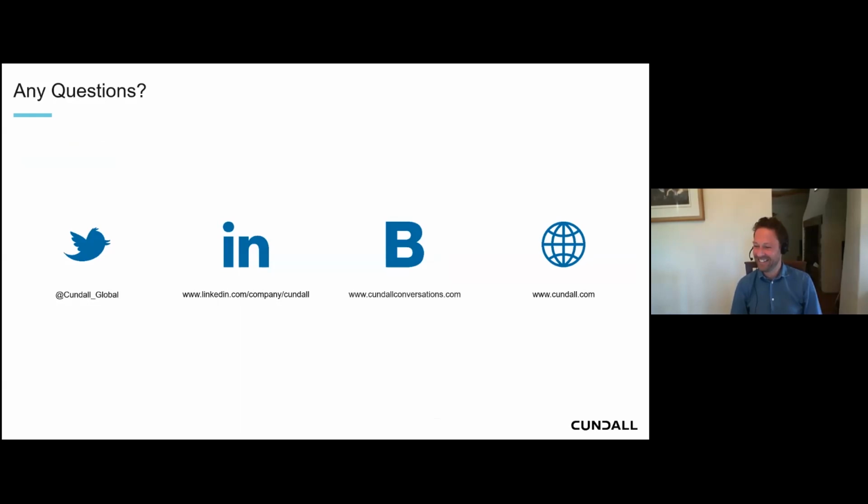So from Olga: as we decarbonise the grid, will the issues of embodied carbon not reduce in parallel? It will to some extent. So I think it's important when you put carbon databases into your models and your decision making that you update those on a regular basis, because some manufacturing processes will decarbonise and that will drive it down. But there's other things there. If you look at the extraction of materials, it's quite hard to decarbonise that presently, and transportation, because they're generally fossil-based fuels. So there's a way to go on those before they're fully electric, although there are moves that way. But taking cement, there's a chemical reaction that occurs as well. So a large part of the emissions of cement are directly linked with the chemical process.